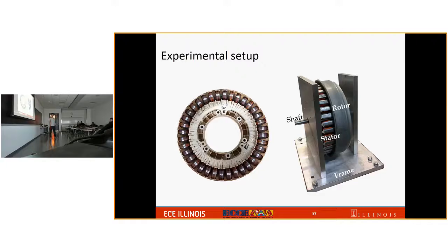The second point is about the thermal. We see that, of course, there's a mismatch between the amount of power coming out from the active rectifier and the amount of power coming out of the passive rectifier. But we need to have some design consideration to make the port providing power to the active rectifier be able to handle that power mismatch. So that is the design consideration for the generator.